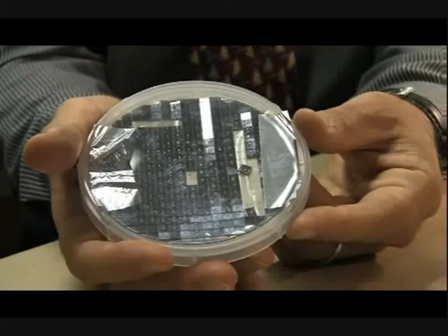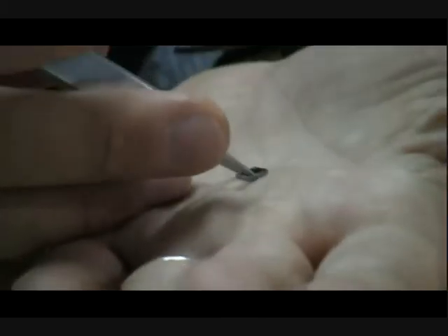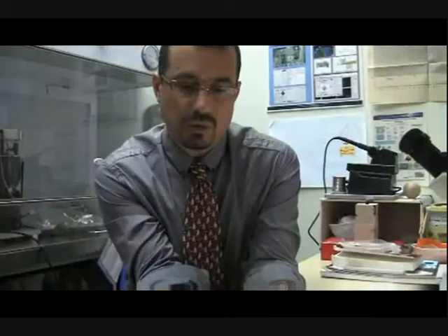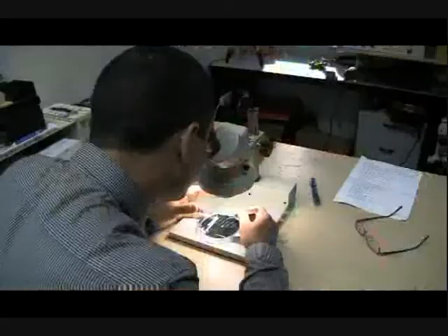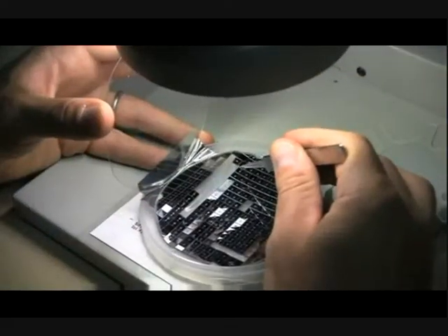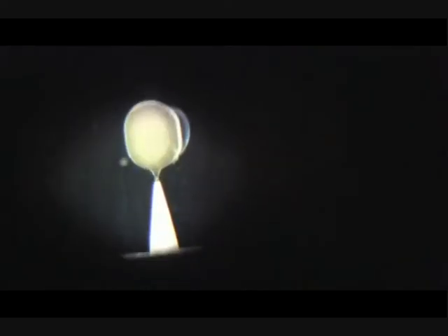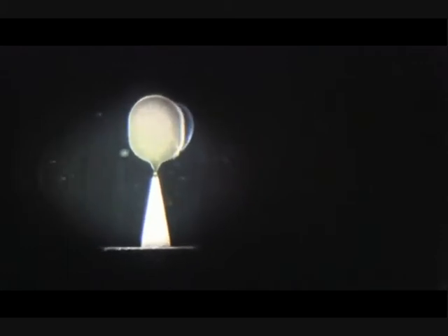Here we have a wafer of micro nozzles. See, each of these little squares is a microchip, and it has one supersonic micro nozzle. This nozzle has a convergent-divergent shape, it is a channel. At the inlet we insert pressurized gas, and the gas is accelerated, it achieves supersonic speed, and it creates a small force. We talk about forces in the order of micronewtons, between a few micronewtons and a few millinewtons, forces that we can control in intensity and duration.